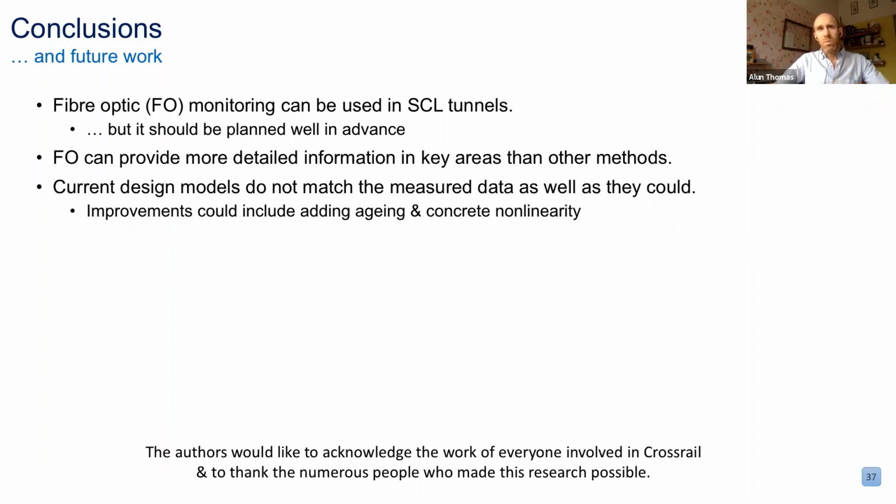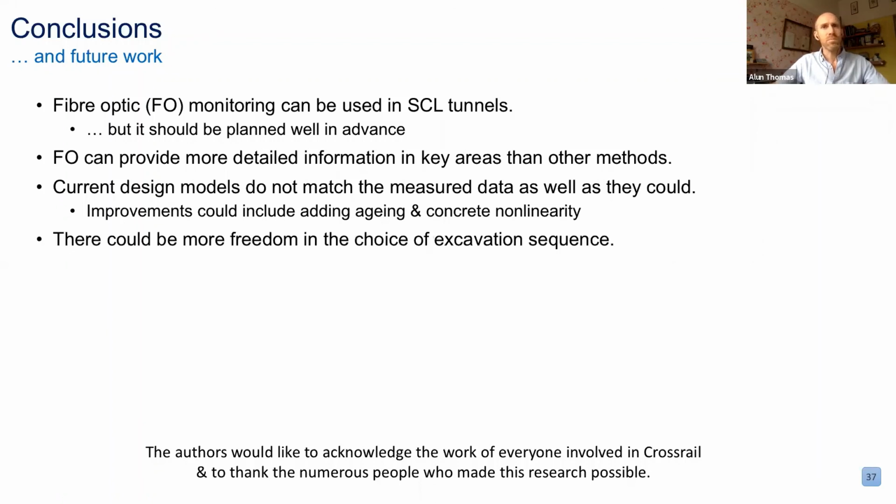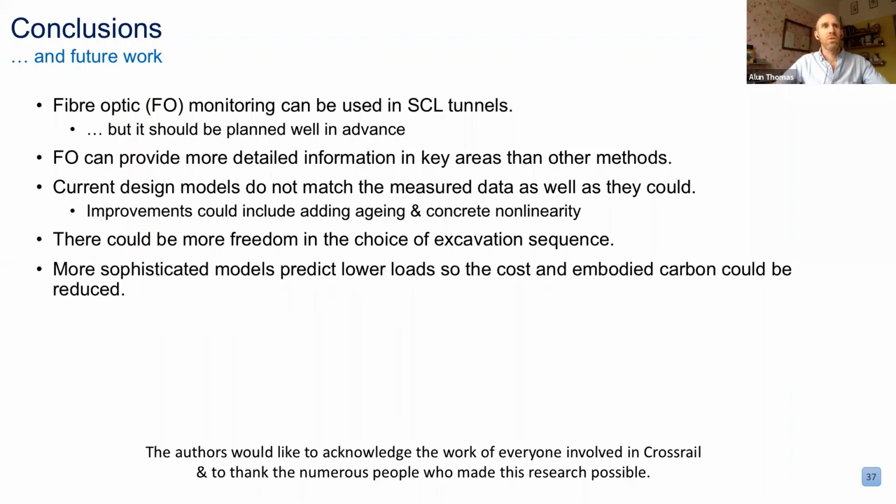Looking at the modelling, we can see that there's still a gap between what we believe is happening, what we've seen measured, if we assume those measurements are completely accurate, and what we are predicting. So there's an area to look at. Non-linearity in the concrete could well be the answer to some of that. There's some scope to play with excavation sequence. Maybe we don't even need the pilots at all, and that would make it easier to build these tunnels. And we could also probably use better design methods to reduce the carbon footprint as well as the financial cost of what we're building.